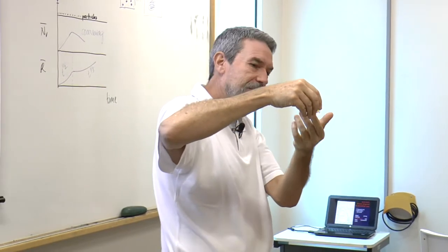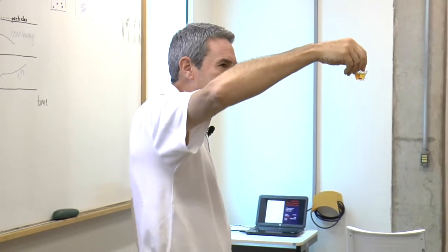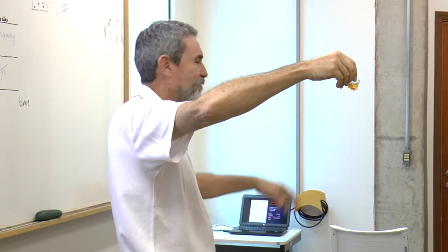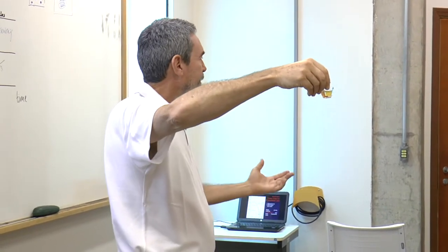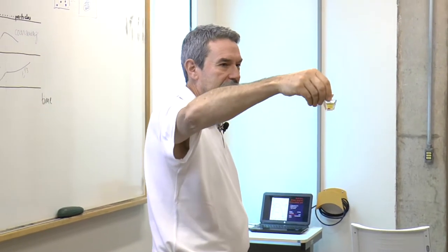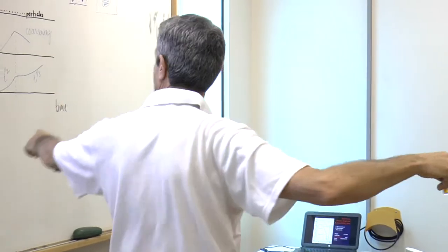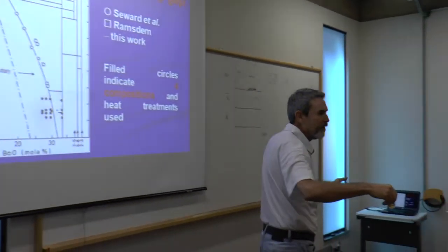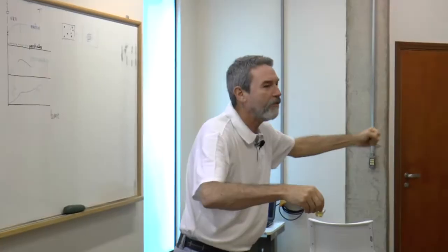It's a liquid. What's the viscosity here, you think? You have attended our viscosity class. What's the viscosity, more or less, of this thing here? About 10 to minus 2 Pascal-seconds or so. It's like water, right? You cannot do this in a glass-forming liquid. The viscosity of this liquid at about Tg will be 10 to the power 12. You can shake it, but nothing happens.